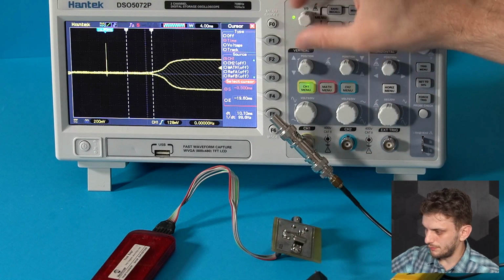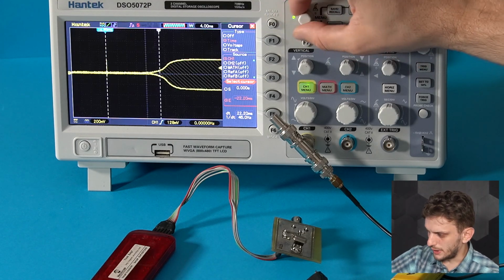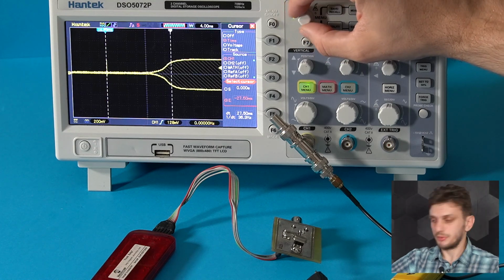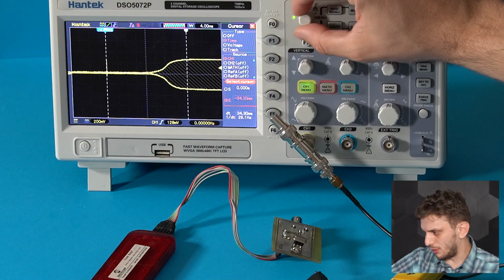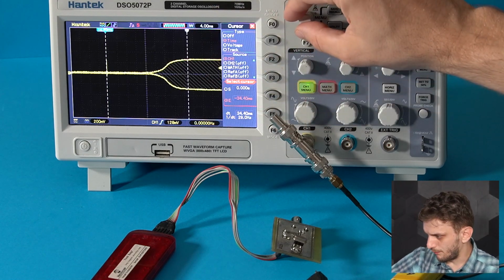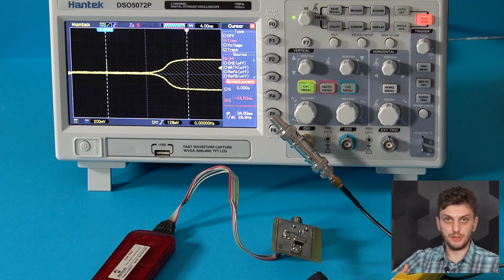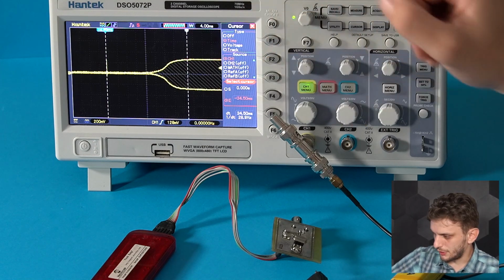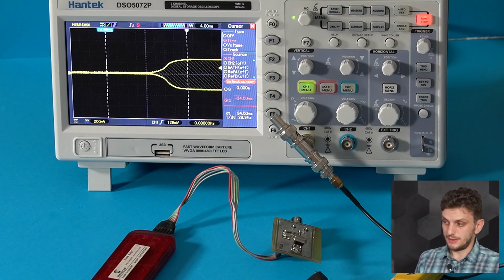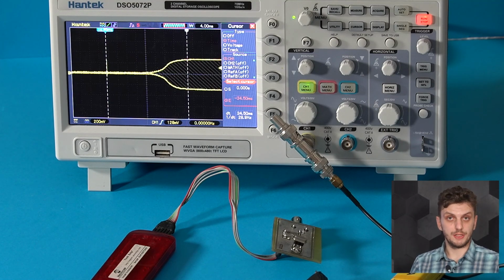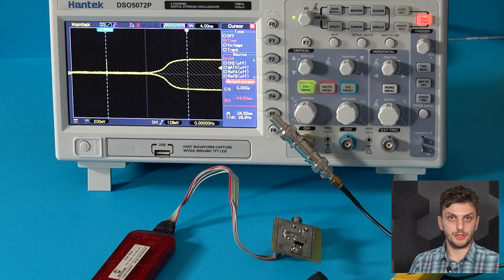So what we're interested in is the timing between this supply event and when our oscillation gets to about 95%. So you can use automated measurements for this, or you can eyeball it and say, well, it's around here. So after about this point, the oscillation is flat, there's no more amplitude increase, and we can see that we have 34.5 milliseconds in between the two events. So this is quite a slow startup for an 8 MHz oscillator. But this is the value that we're getting with the current configuration.